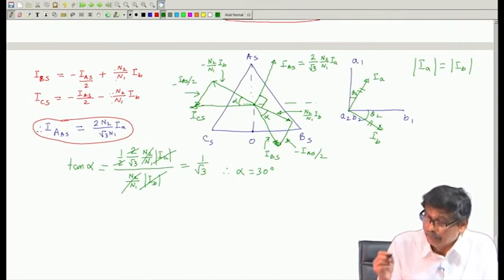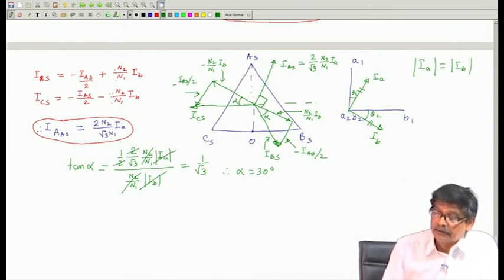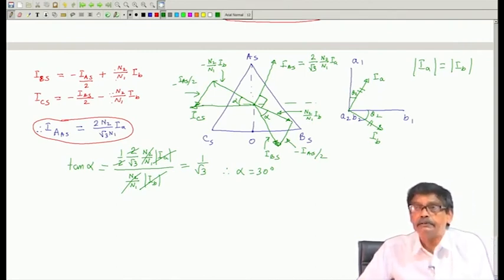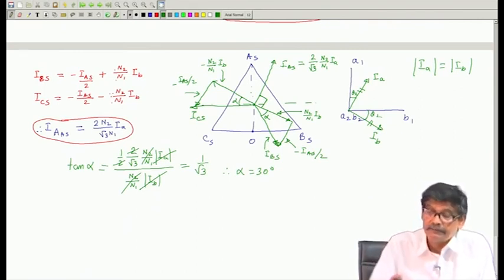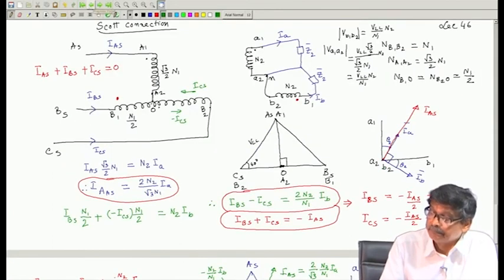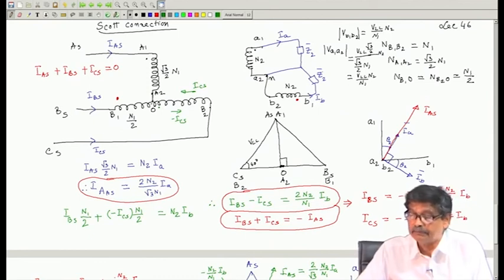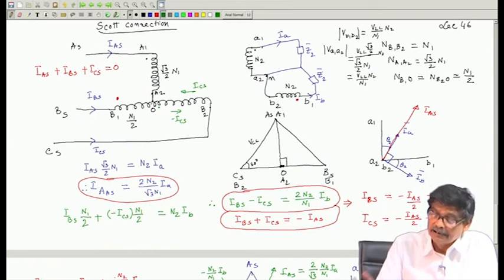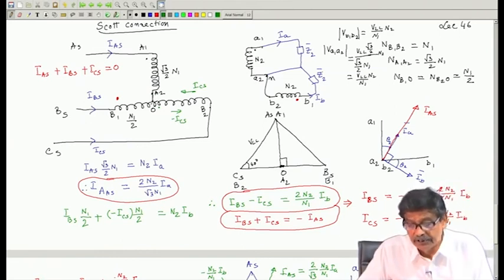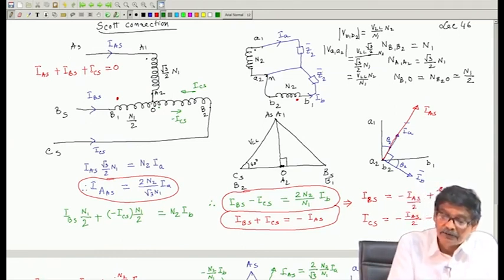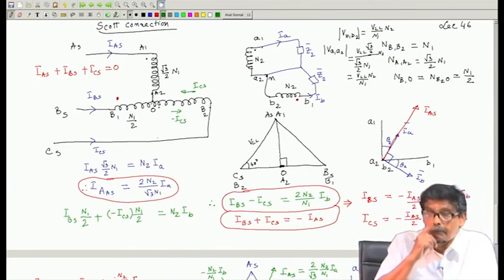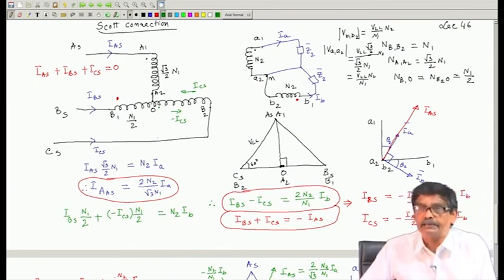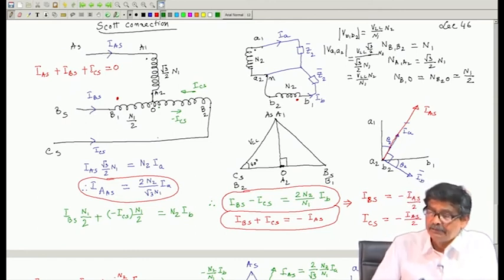Therefore, we conclude that when the secondary current is balanced two phase current like this, when Z2 are same both in magnitude and power factor angle, then secondary current will be balanced, but it will also ensure that the current drawn from the three phase side will be also balanced. So, it is a very nice connection.